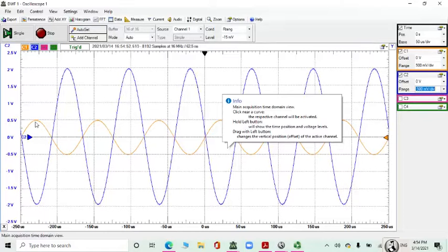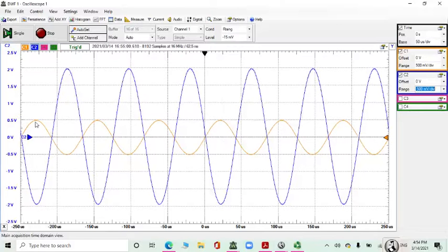Your gain is negative R2 divided by R1. So if you divide 20 kilo ohms by 5.1, or theoretically 19.82 divided by 5.05, it's almost 4, less than 4, maybe 3.9 something.